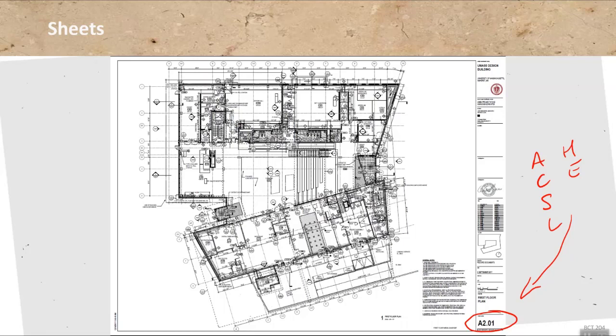And often they're supplied by consultants, and they may look slightly different, but they're usually assembled in that larger sheet set. Okay, so next to that letter is a number, and it's somewhat consecutive. Sometimes it's 100, 200, 300 or something like this. In this case here you see 2.01, so there's some kind of a sub-numbering scheme there too. It's often or it can be different, and it is very much up to the designer to come up with a system and stick to it for that matter.